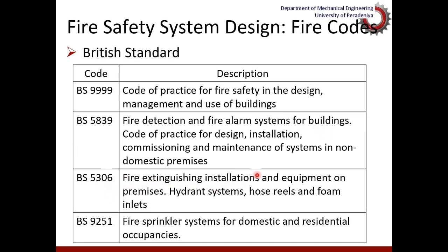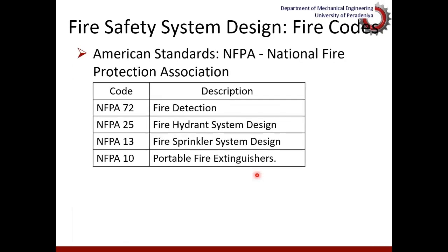And for mechanical related systems, heat and air conditioning systems or fire systems or things like that, there's a greater tendency to use American standards than Euro and British standards. But of course, in Sri Lanka, we use Euro standards also. And there are British Euro combined standards for fire systems. But these American standards are also frequently used. For example, for air conditioning design, usually we use the ASHRAE code, that is American. And for fire systems also, quite frequently we use NFPA codes, National Fire Protection Association, which is again an American system.